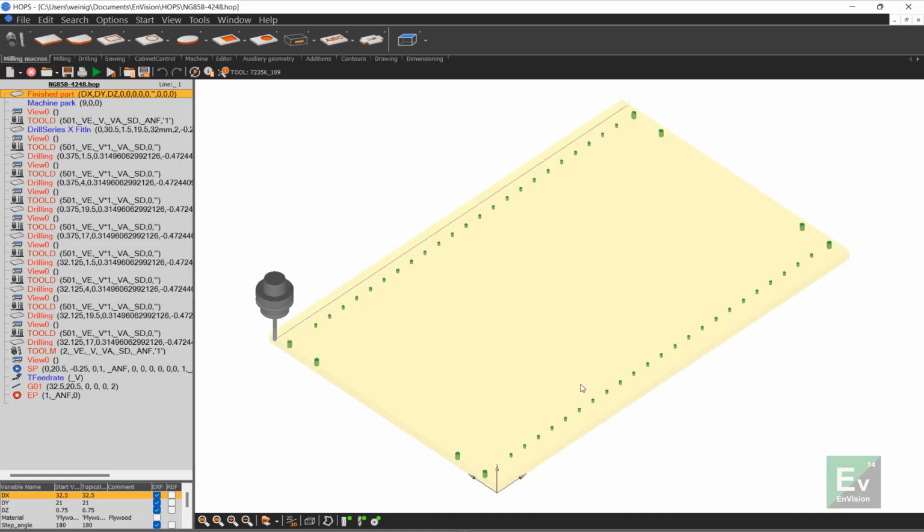We can see an example of one of the wall end panels that we've created. We can see we have our dowels, our dado construction, the shelf line boring, etc. And all of that machining is user definable. So if that doesn't match the specifics of how you create your products, then we can manipulate the templates so that it matches perfectly with your product.